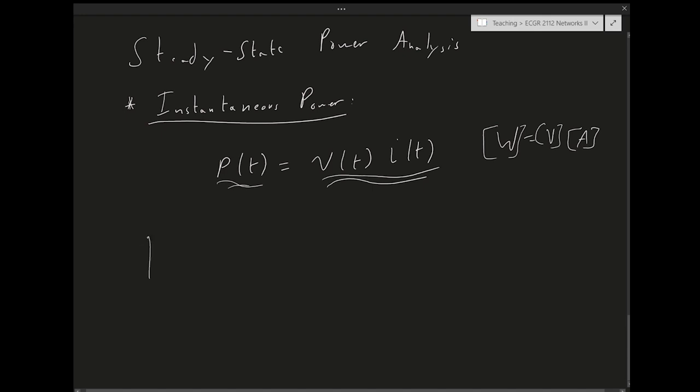So if I have an element and my sign convention is as follows, V, and then the I is going in, right? Then when I calculate P equals VI, this configuration of the signs and the arrows for the current designates an absorption, because the current is going into the element. So this is the P absorbed by the element, the power absorbed by the element.